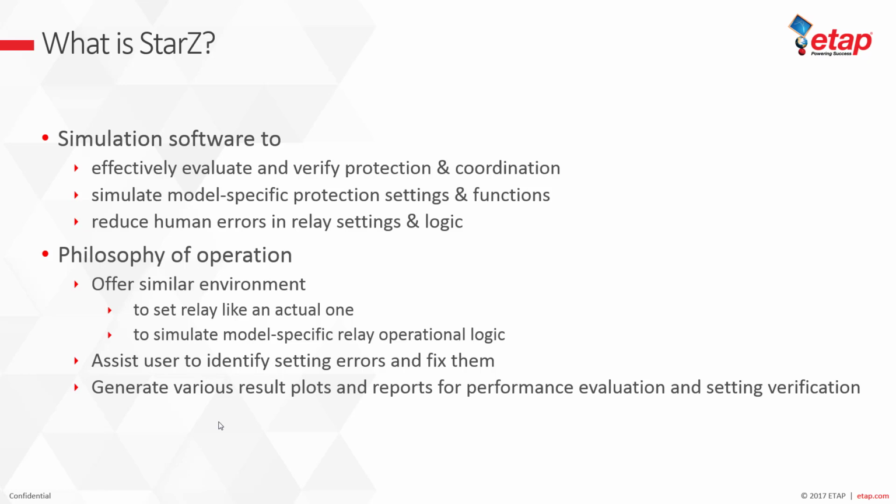The user can also set and simulate scheme logic, relay interlocks to other protective devices, and relay communication on top of the existing protection elements. In addition to model-specific relay models, ETAP provides a generic model which can be utilized to simulate general distance protection function for system analysis where a specific model is not required.